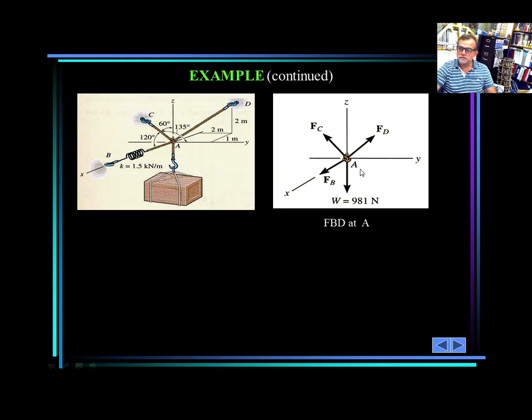Once again, the same way. I'm gonna start force by force. For example, force B. The only thing I know about the force B is that it goes in the I direction and it has only one component. How do I know? Because it goes only in the x-axis. So one direction, force B, there. In the positive direction, so my force B is gonna be FB magnitude multiplied by the I direction, which is the unit vector.